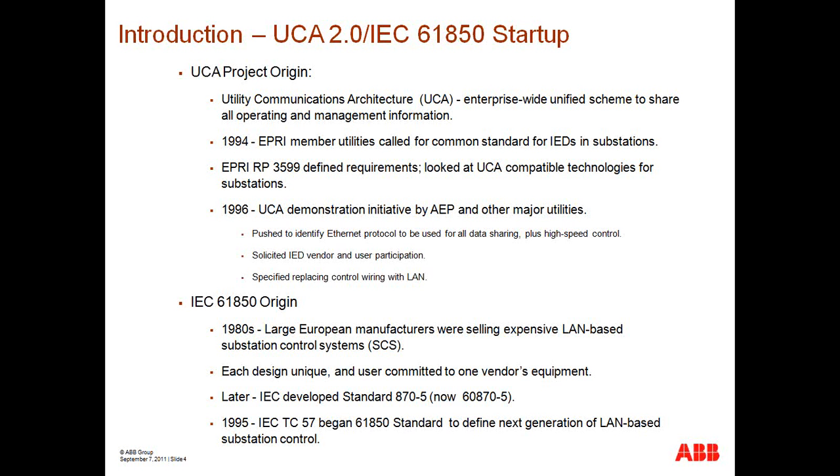So, IEC 61850 and its origins. When looking at IEC 61850, it's really the convergence of 2 different initiatives that were ongoing during the mid-1990s around the world. One was being run in North America by the UCA, which stands for Utility Communications Architecture Group. And then in the IEC world, we also had working groups inside Technical Committee 57, which were exploring the need for a standard communication protocol for substation automation applications.